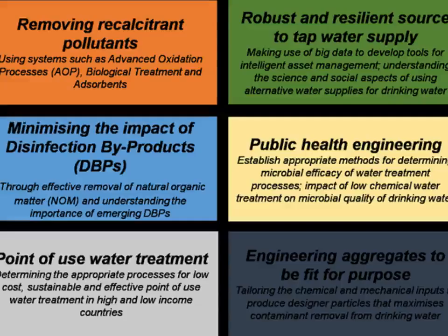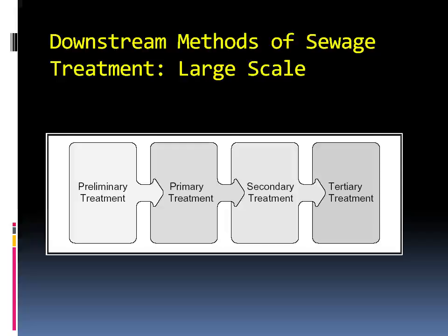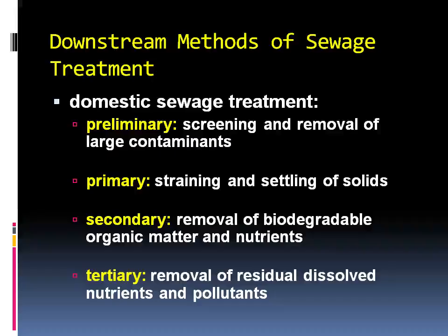Now we'll see some water pollution control systems. The most common form of water pollution control consists of a system of sewage and wastewater treatment plants. Wastewater is collected by the sewage systems and delivered to the waste treatment plant where it is made fit for discharge back into the general water supply. The discovery of more pollutants is causing serious questions to be raised concerning the real meaning of the term fit as used here. The process of treating municipal sewage has been broadly classified as primary, secondary and tertiary level.